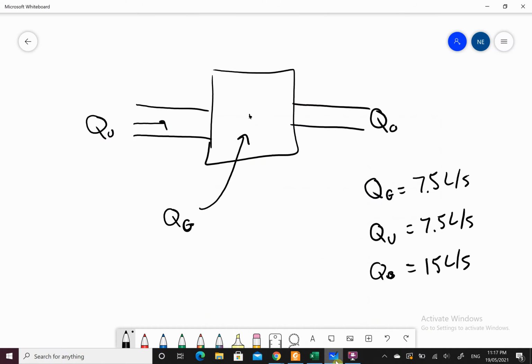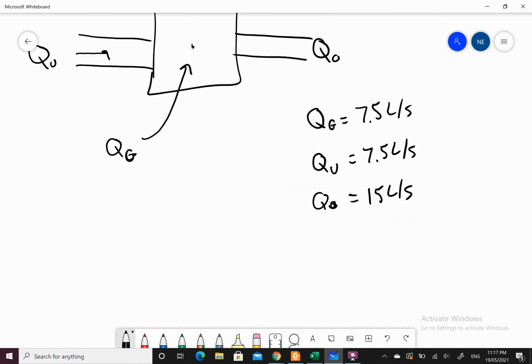So what I can do now is I've worked this out. K is equal to 2.1. That's my head loss coefficient for the pit. So the shock loss that occurs in the pit, that's the coefficient that I'll use there. And what you know is the head loss in the pit, or the other side of the pit.